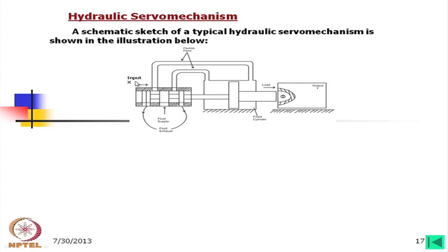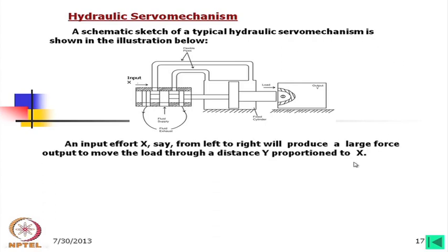When we give an input, then the load moves, but looking into position and motion, the valve body, outside body also moves, and by that closing the motion of the load, and again with the presence of input, the spool will move further and the load will be moved. Now, if there is a feedback control within this system, then we shall call it a servo mechanism, and there is a wide application of hydraulic servo mechanisms, starting from machine tools to many others, even in missile control.